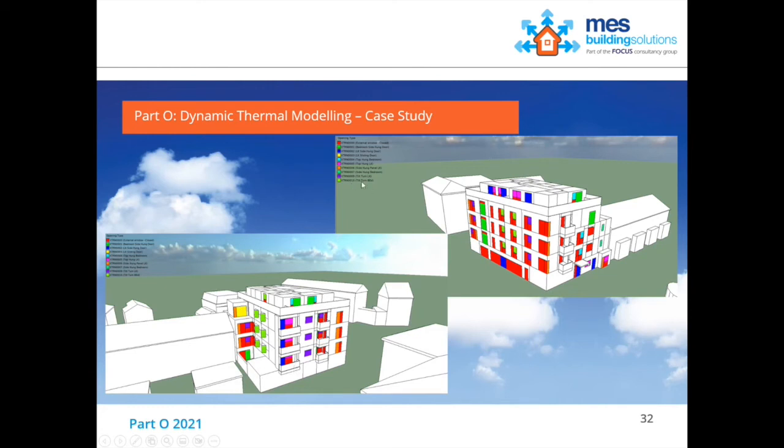So as you can see, some of these are tilt and turn, fully openable windows. We've got some doors over here. They've then got elements next to them which are top hung. The red ones tend to be fixed. They are all fixed panels, closed windows that can't be opened. These all have their relevant characteristics applied to them, so we can say what the free area is. And then the software can model the movement of air through those spaces as part of the calculation.